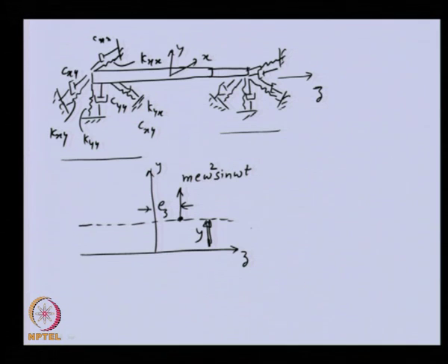the shaft. Now, at the ends bearings are there, they will give forces. This time the forces will not be only from the spring, which was the term we used in the previous analysis, but now because of the cross coupled term we will have some more terms, due to the displacement in x direction, because cross coupling is now there between the two linear displacement directions.